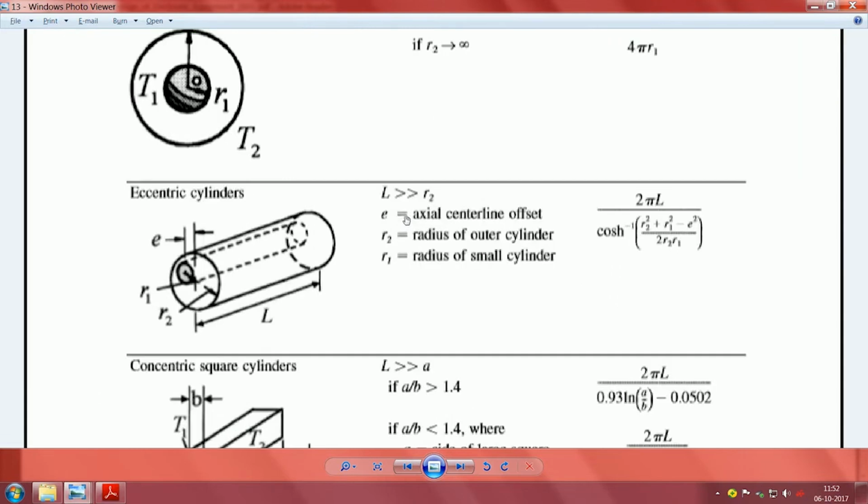In the first lecture I showed you, we made a temperature compensated pressure sensor. So, I have a pressure sensor at one point, and to compensate for it we have a small PN junction sensor in it, all of them mounted in a thermal block.